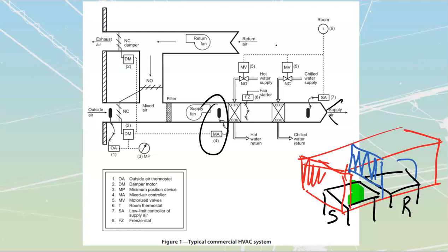It is going to be downstream of my filter and of my fan, and it is going to try to maintain a set temperature inside here that is usually going to be a target of 13 degrees. Now, these are hard and fast numbers for most commercial systems because usually we've got a set temperature inside of a building of 21 degrees. Through years of trial and error, people have discovered that maximum efficiency of these systems usually happens when I start with about 13 degrees here. That way, if I've got to heat or cool, I'm not too far out from either one of those.